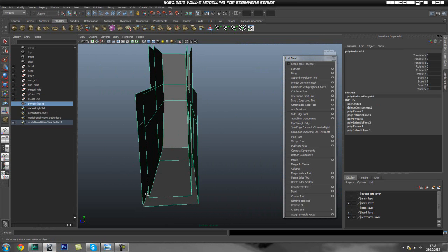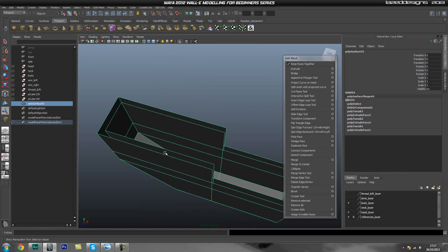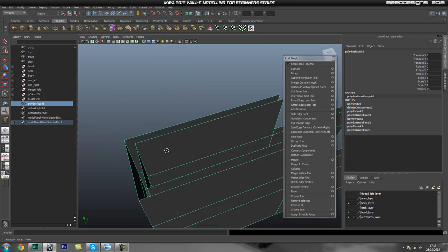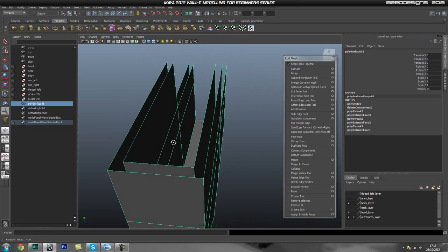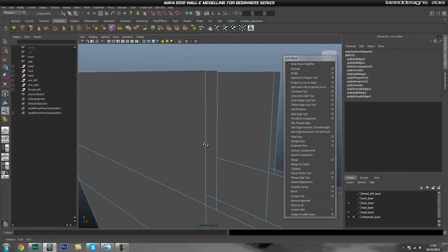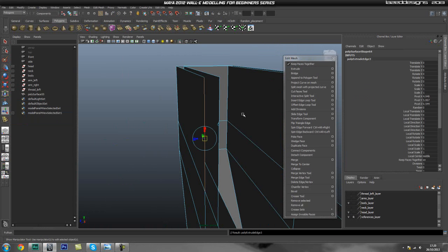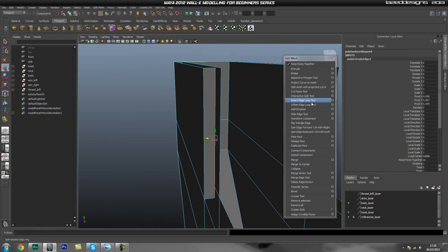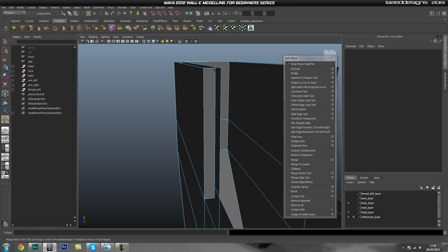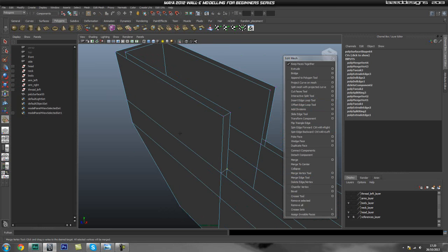Now basically all we got to do is join up these faces, okay? So that shouldn't be too complicated, hopefully. So we're going to start off with this edge around here, I think. That should be alright. And let's go ahead and extrude it. Move it. Okay, and then just use a merge vertex tool to snap these to the right place. Okay, so that's filled in.